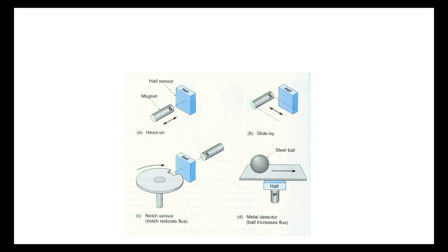These might go bad, but, you know, odds are these will last longer. We don't have to worry about friction, right? You understand? Because they what? The magnetic field and the sensing element are not actually making contact with each other. So a Hall effect sensor doesn't sense metal. All it senses is magnetic field. And so you notice this is some things they do where they appear to sense metal, right? You understand? Where they appear to sense metal.